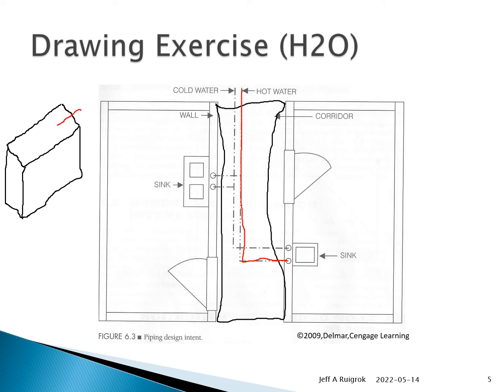So I'm going to come down here, and then I'm going to go to the right, and then come down in the wall. So that's all the drawing shows, that 90-degree down, and you don't know what it does. But again, as a plumber, you'll realize this also has to come out of the wall, which would be this piece here. So there's another 90 at the bottom, and it's just all hidden from view. And then the pipe coming out of the wall has to be added.